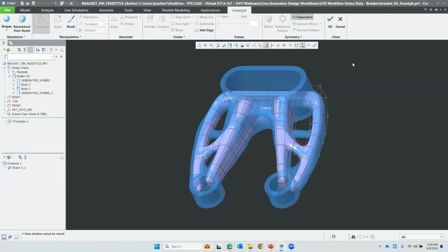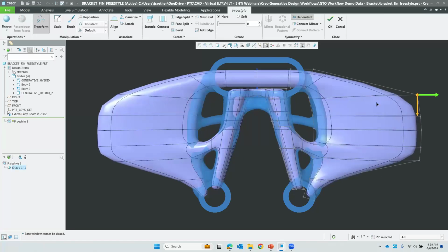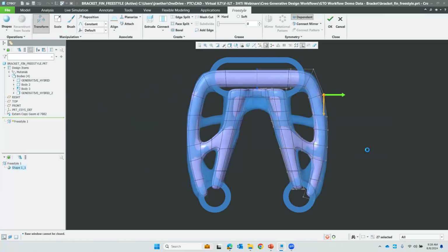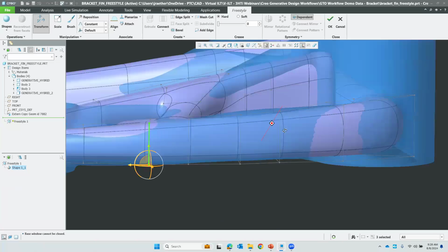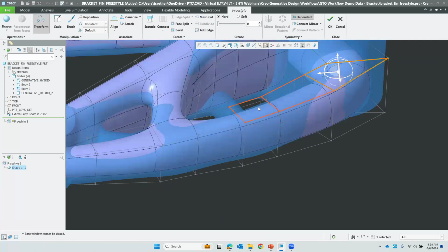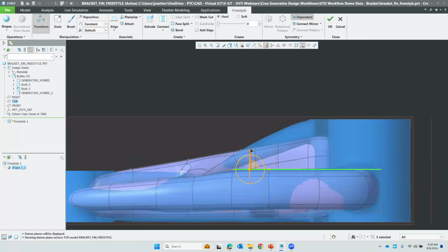And this is just a really easy way to create very high quality surfaces really quickly. Instead of creating curves and whatever, I'm manipulating a primitive shape. So I can take any entity, simply grab it. I can grab an edge, a face, a vertex, and we can begin to make some quick changes to it. So if we look over here, maybe we see that we're off. Let's grab this, hold down the shift key and take these. If we set that planar, let's turn on our datum planes and set it planar to there. Now I've got something we can go ahead and match and do whatever, right?